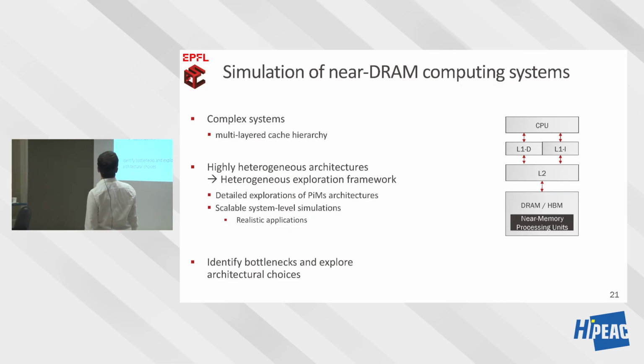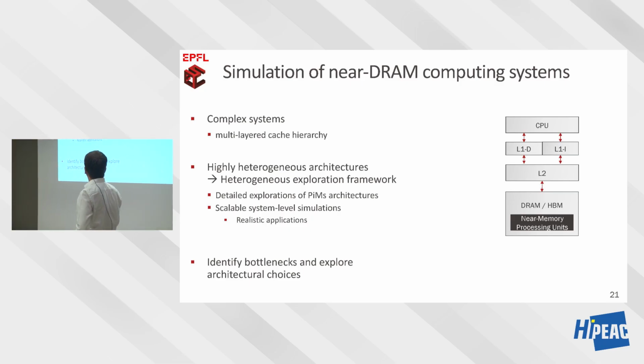So what we do is define a near-DRAM processor as a SystemC module, which can be synthesized and also integrated as a component into a gem5 simulation, so that we have this dual nature of system simulation on one side and path to fabrication on the other.